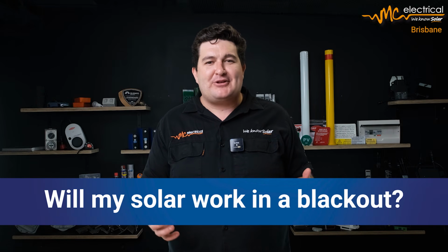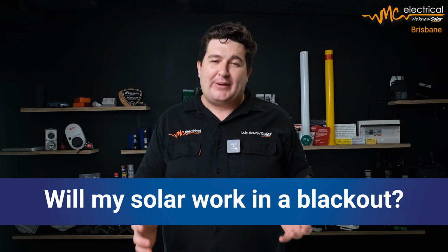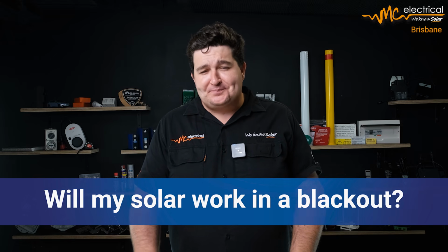Another really common question I get asked is, okay, I don't have a battery, but I've got solar, so surely if I have a blackout and the sun is shining, I've got power. Well, the reality is that these are grid-connected systems, and so if there's a blackout, maybe it's because there's a power line down or somebody's doing work on a line, these systems have to turn off. So if you don't have a battery, you won't have power even though you have solar and the sun is shining.